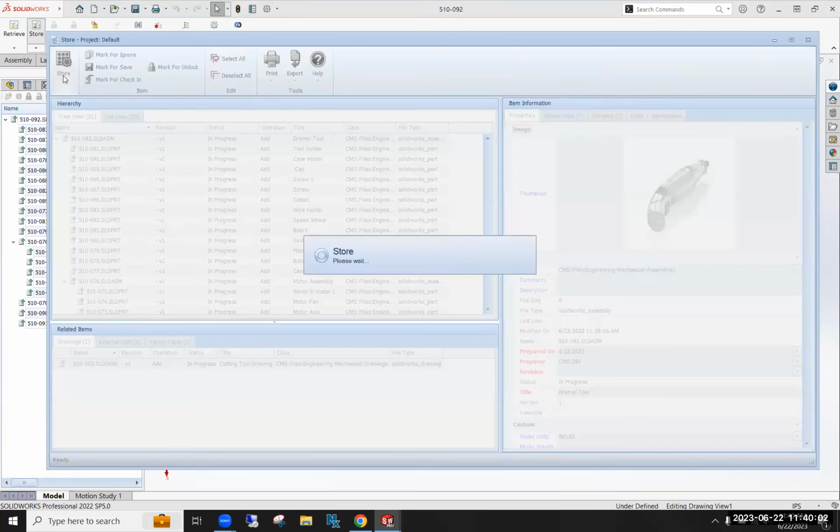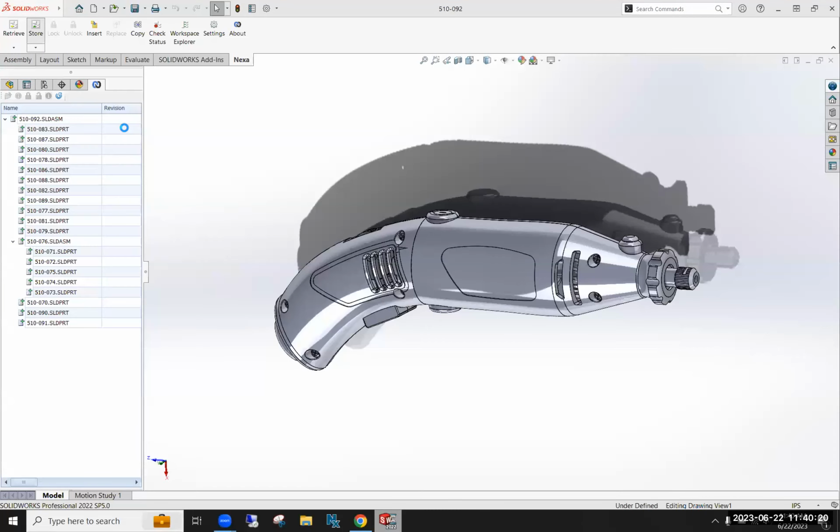Let me go ahead and store this. After this is stored, I'll show the Workplace Explorer. Once again, show that that's filled out. And then I'll export the BOM and I'll show the web page to import BOMs, show that functionality. And then I will also pass that back off to Hunter, and he will show how to incorporate both Creo and SolidWorks files into one assembly.